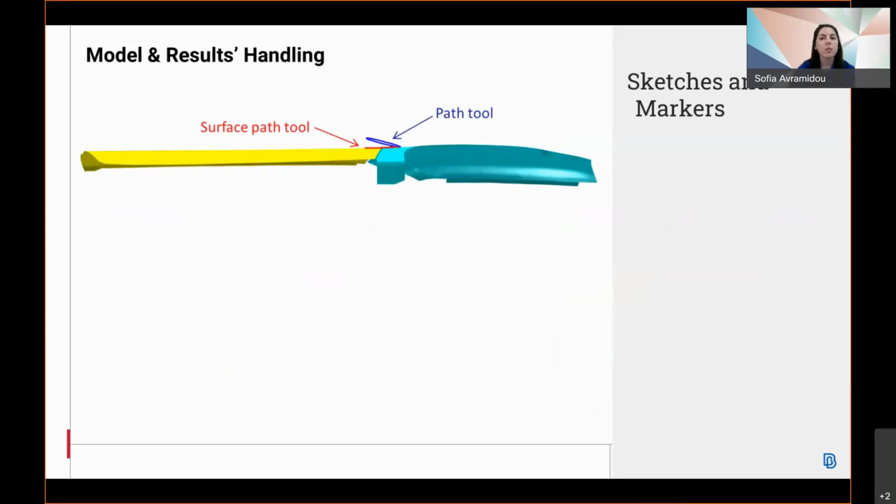A new type of sketch is now available in the sketch tool. This is a freehand sketch which gets attached to the nearest PIDs and stays attached during model handling. The difference can be seen here, where the red sketch has stayed attached to the PIDs when rotating the model, whereas the blue one hasn't.